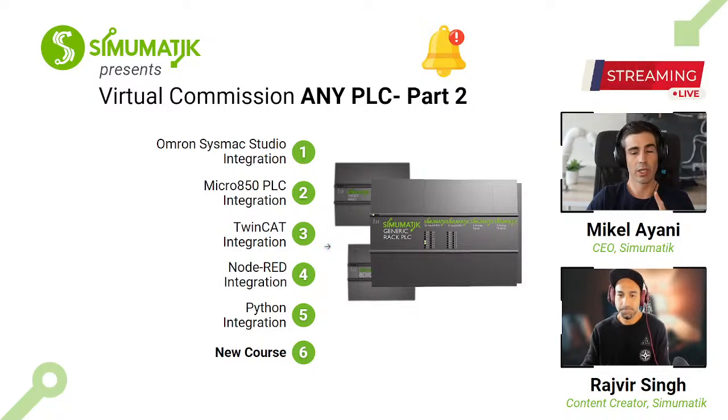I will do the TwinCAT integration. This will again be a specific integration. TwinCAT, or Beckhoff, has this ADS protocol, so we won't be using standard protocols like OPC UA or Modbus. Both in Omron and TwinCAT, it will be very specific native protocols that we have in our gateway. You will see it's going to be super easy to do the connection.